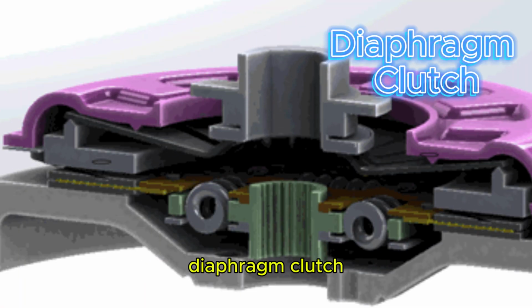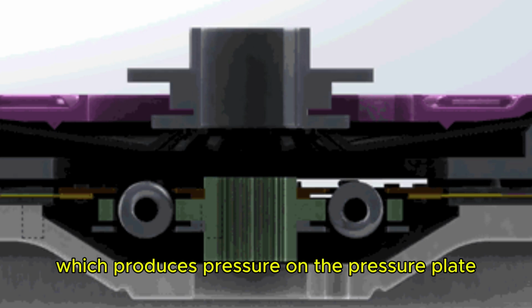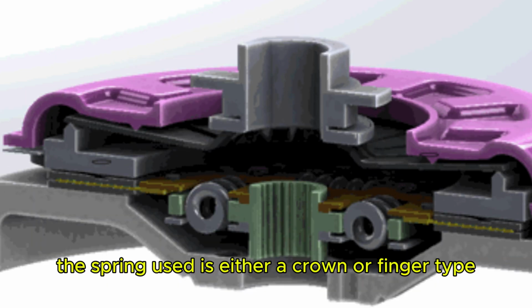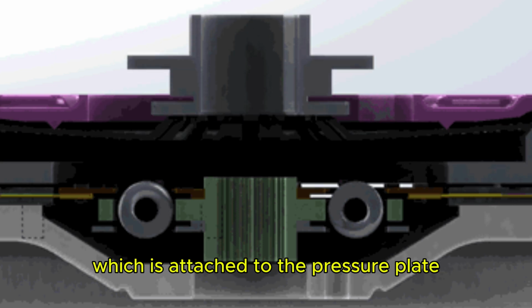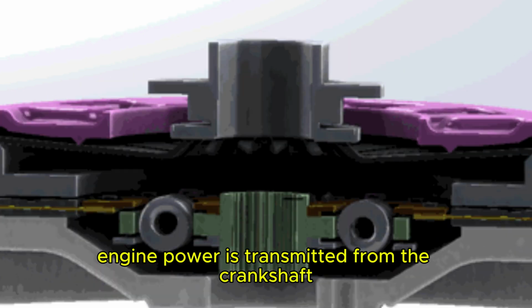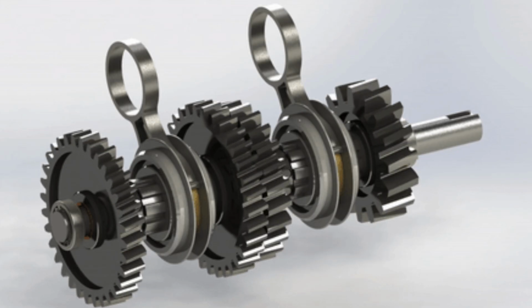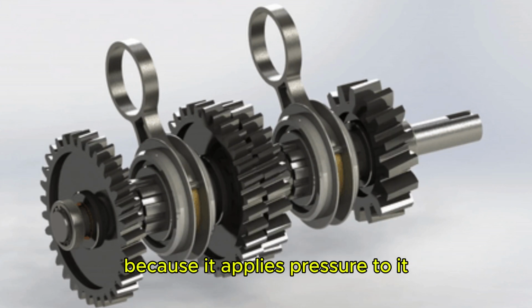Diaphragm clutch. The diaphragm clutch contains a diaphragm on a conical spring, which produces pressure on the pressure plate for engaging the clutch. The spring used is either a crown or finger type, which is attached to the pressure plate. In this type of clutch, the engine power is transmitted from the crankshaft to the flywheel, which contains a friction lining. The pressure plate is located behind the clutch plate because it applies pressure to it.